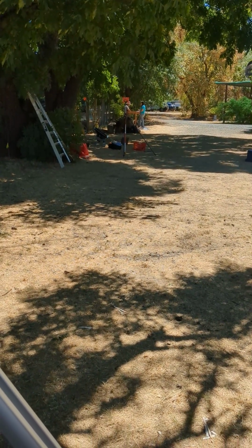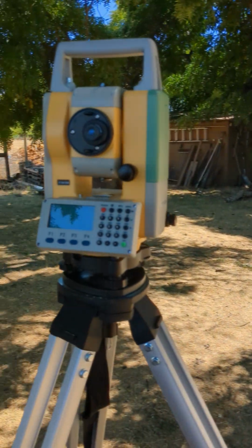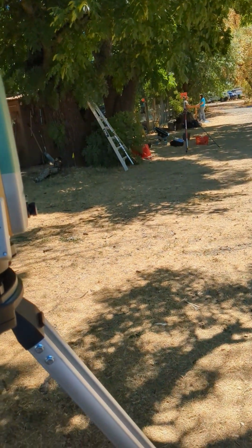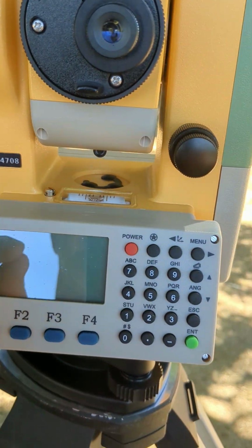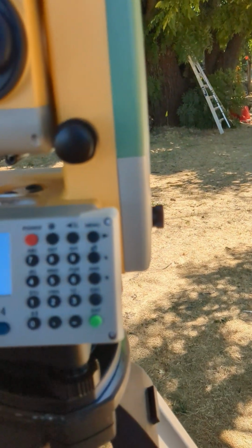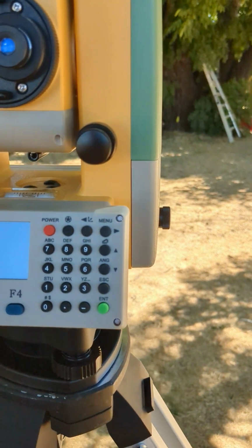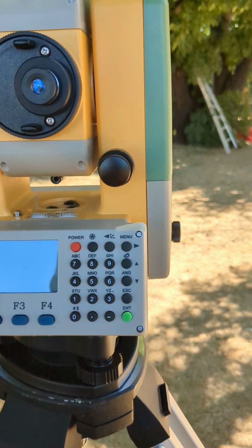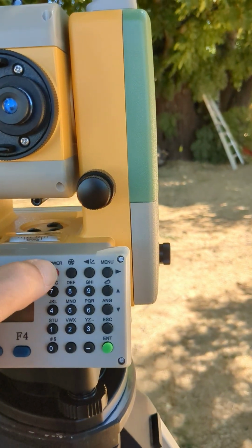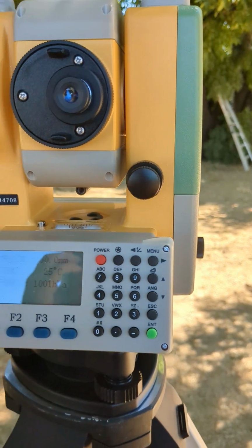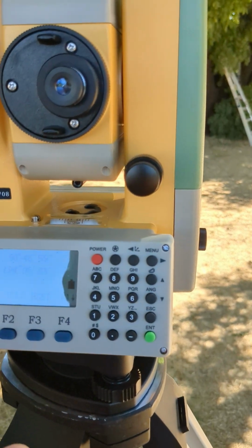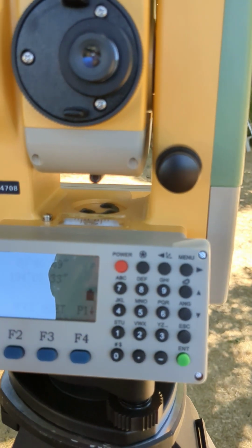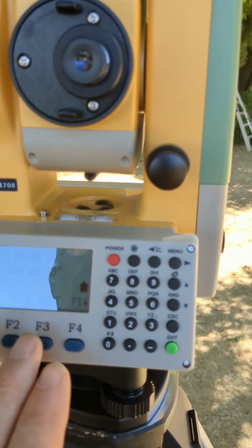Okay, so there's the target. I've successfully swapped these locations. That one's vertical, there's a bubble on it. This one is now leveled. You can see at the top here in both axes. And I actually powered it off so we can assure to start in the same spot. So I'm going to reach up here and turn power on. The first thing power on, I had actually had power on earlier because I used the laser to get this guy located. First thing I have to do, or I would like to do, is do the 0 set or horizontal set.